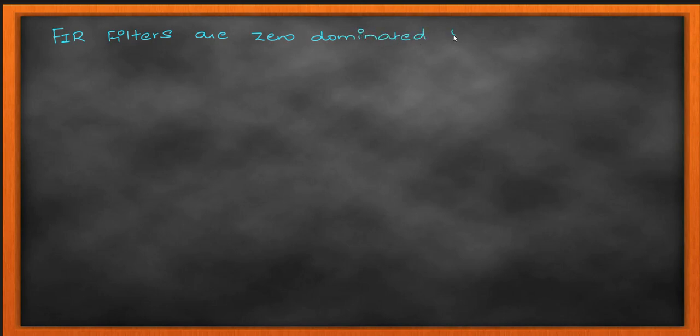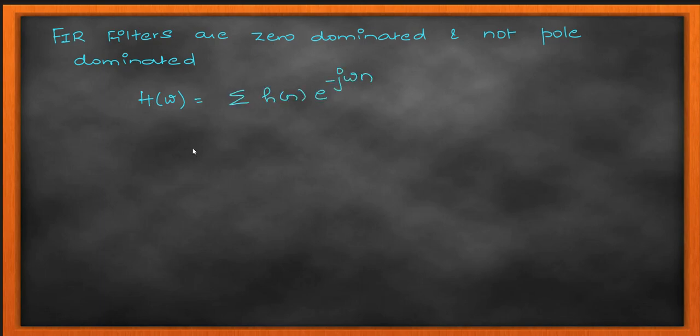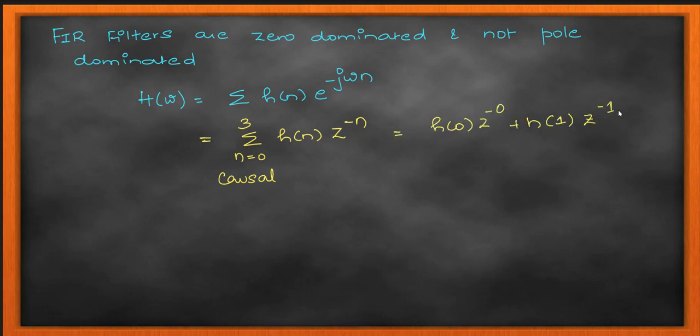Alright, we will be seeing this later on in FIR structures. We will be seeing some filter structures for FIR, and there I'll be telling you why causality is an essential condition for your FIR filter, because it comes in the realization of the filter structure. When you want to convert these FIRs into an actual hardware prototype, you have the realization problem where you cannot use those non-causal terms. We'll be seeing that in the coming lectures. For now, we'll just see the definition of causality, and also know that causality is an essential condition for your FIR filter.